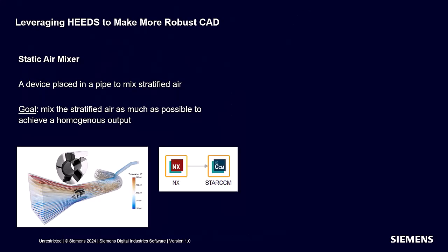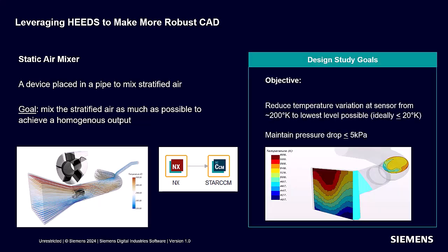This is a computational fluid dynamics problem where, using SimCenter STAR-CCM+, the virtual performance can be assessed for a given device. Ultimately, our optimization goals with HEEDS are to minimize the temperature variation at a cross-section downstream of the device while maintaining a pressure drop constraint threshold.